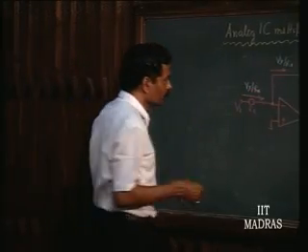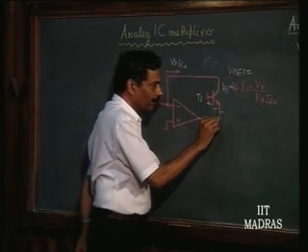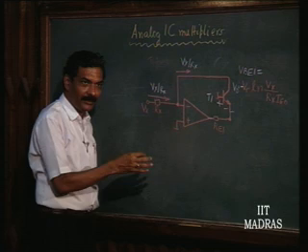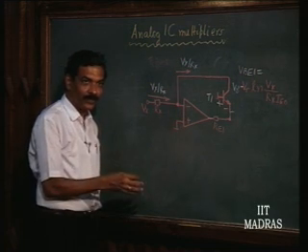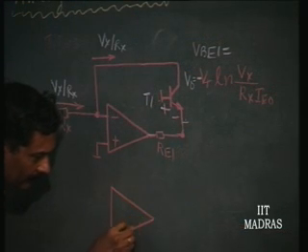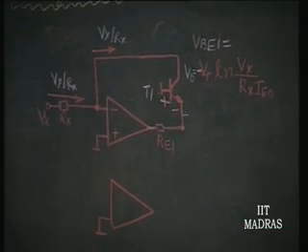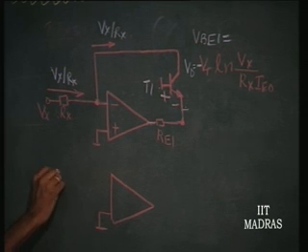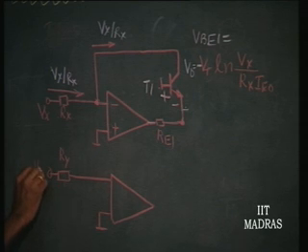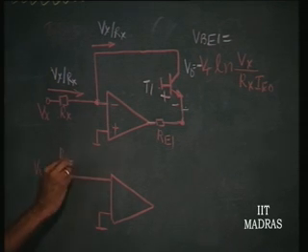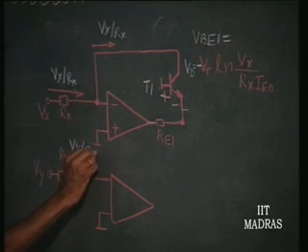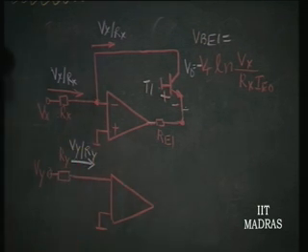Now, we have got the required voltage. Now, what should I do? I should add to this voltage the log of another voltage which is Vy. That again is going to be similar to this. So, I will take another voltage here that will be Ry, this you get Vy, and the input current now here in this is going to be Vy by Ry,